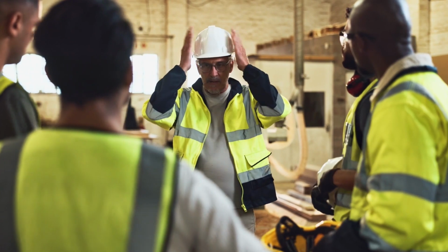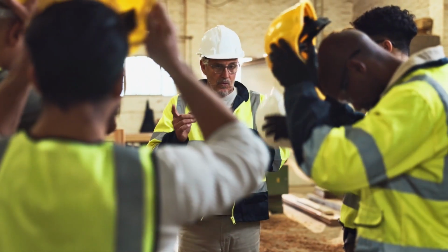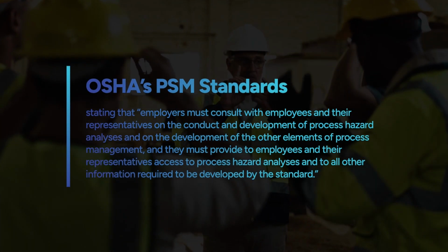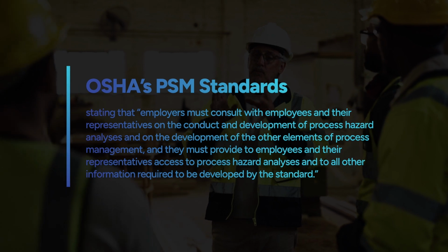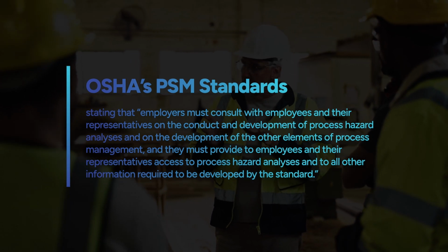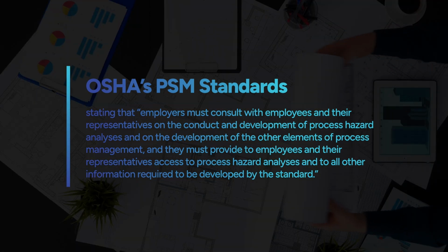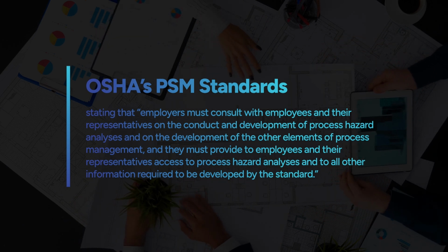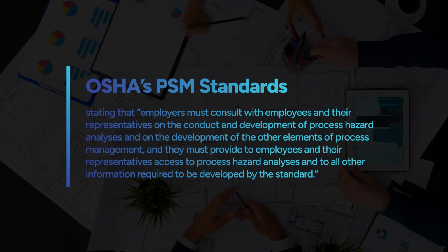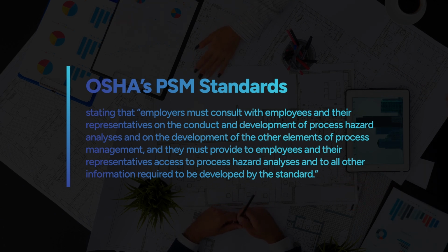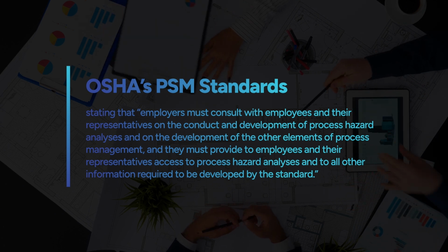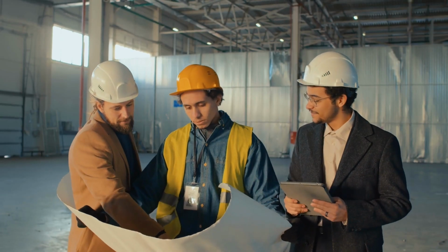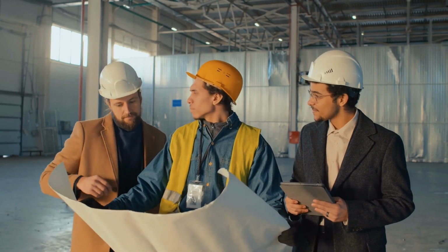OSHA's PSM standards also mandate employee participation, stating that employers must consult with employees and their representatives on the conduct and development of process hazard analyses, and on the development of other elements of process management, and they must provide to employees and their representatives access to process hazard analyses and all other information required to be developed by the standard. Employers must develop a written plan of action to implement this requirement.